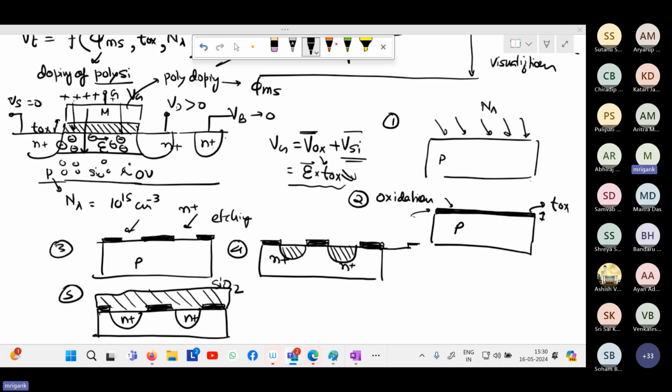this one. So in order to etch open now and create the contact, I will again etch these areas and deposit metal. So I can etch these areas and deposit metals so that I have the contact to this source drain region. So this red color thing that I'm showing, it is a metal layer. So you can have the metal contact going into the source and drain region through this field oxide.